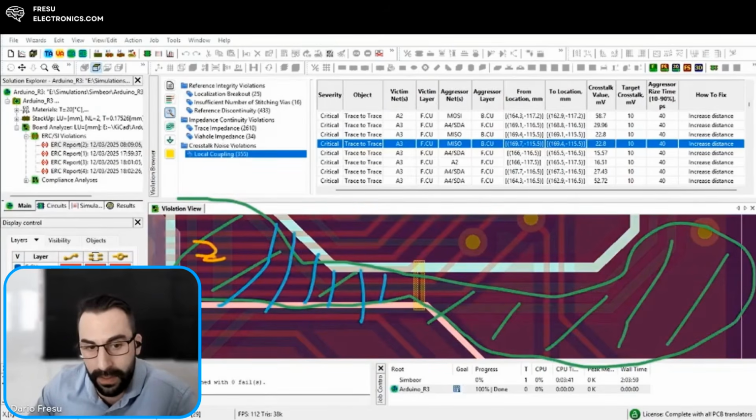This impedance here is what is going to create the common mode issues, because as the fields propagate from this point to this point in the form of displacement current, all of a sudden I have a voltage drop. This voltage drop is going to drive the common mode currents.